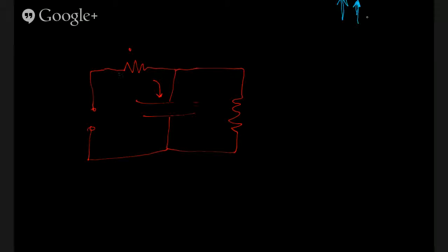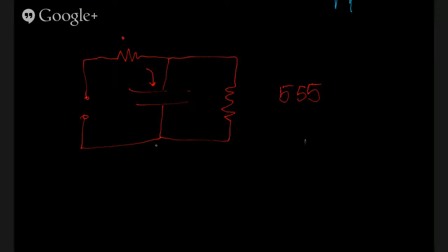So you can control the rate at which the capacitor charges and discharges, and you can end up with audio frequencies like that. Generally pretty regular. There's an integrated circuit called the 555 timer, which is pretty ubiquitous. Basically, the chip has a few pins on it where you put in RC networks, resistance capacitance networks.